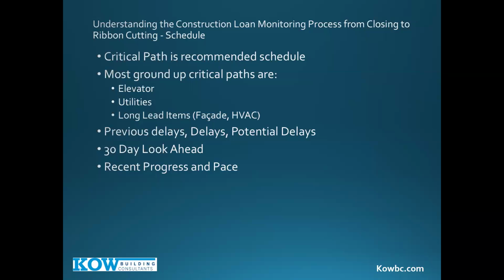You have a bathroom and you have a kitchen, and you decide to get both renovated. And you hire Bathrooms R Us to do your bathroom, and they're going to take 1 month: 2 weeks demo, 2 weeks new install. And your kitchen company, Kitchens XYZ, they're going to take 2 months: 1 month demo and 1 month construction. So your bathroom's 1 month and your kitchen's 2 months. And you start them on the same day. Your kitchen is your critical path.